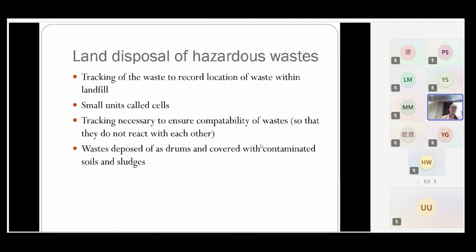So yeah, there are ways to repurpose landfills. You have both hazardous waste landfills and municipal waste landfills, so there are two different ways that the landfills are developed. The hazardous waste landfills obviously have to be designed much more carefully because it's hazardous waste. So usually you will have two sets of liners, two sets of leachate collection systems, and so on, to be able to protect the groundwater even better.